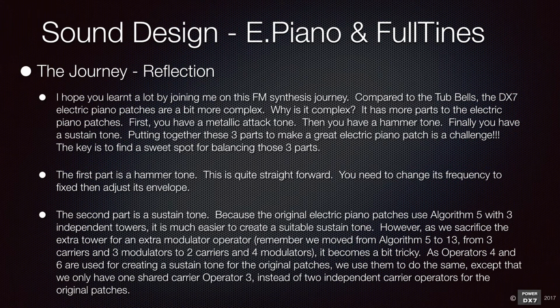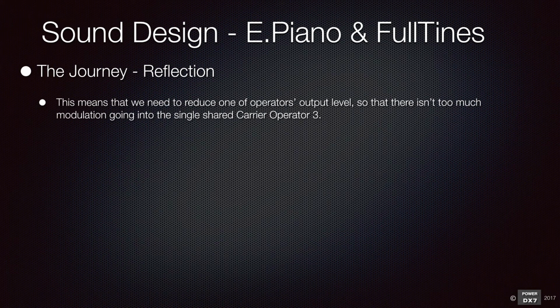It becomes a bit tricky. As operators 4 and 6 are used for creating a decay tone for the original patches, we use them to do the same, except that we only have one shared carrier operator 3, instead of 2 independent carrier operators for the original patches. This means that we need to reduce one of the operators' output level so that there isn't too much modulation going into the single shared carrier operator 3.